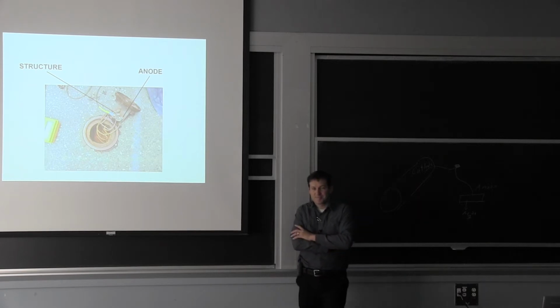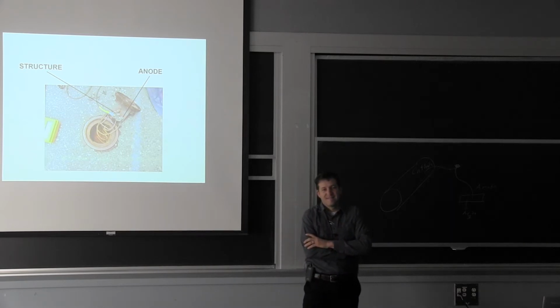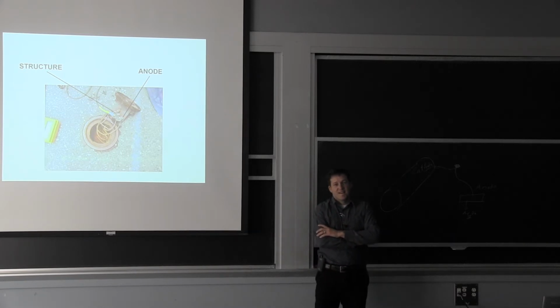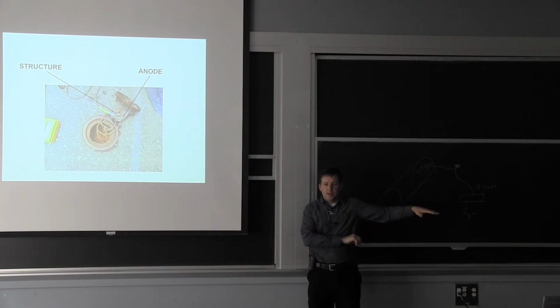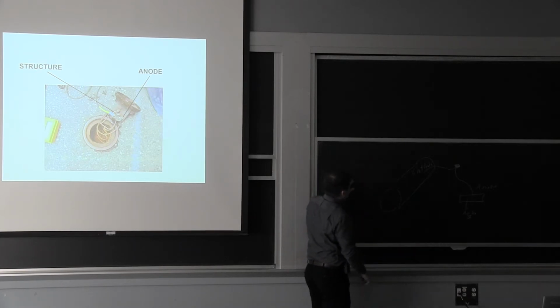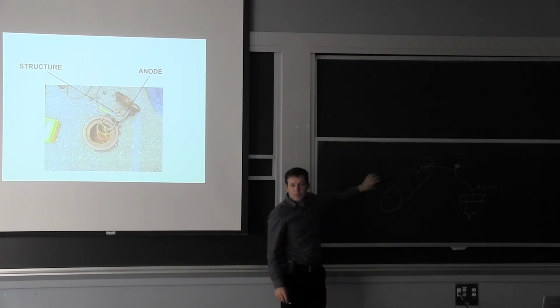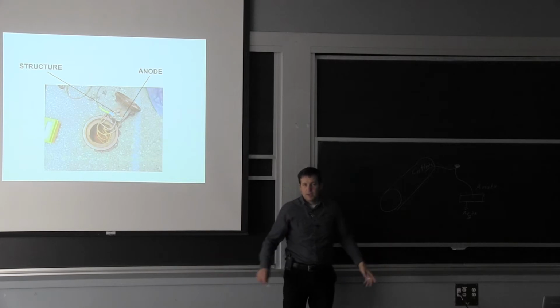Yes? How about vertical placement of this anode? Obviously, you're talking about different stratification of water. You would want to try to have it about the same height because of the water table effect and all of this. So if I put the application on top here, and it's very dry, it's not really going to conduct ions with the structure. So in all the systems I've seen, you essentially have to dig wider, and that's where you put your sacrificial materials.